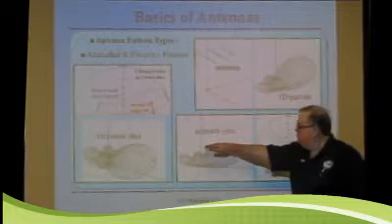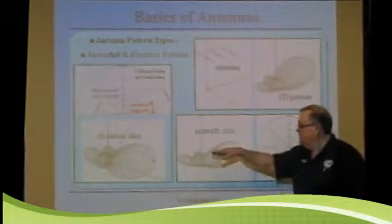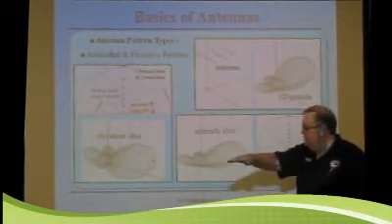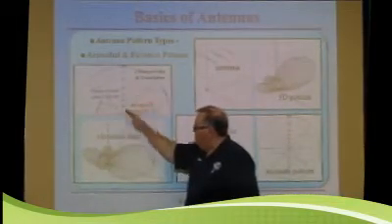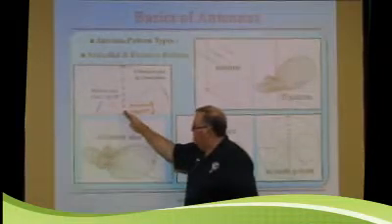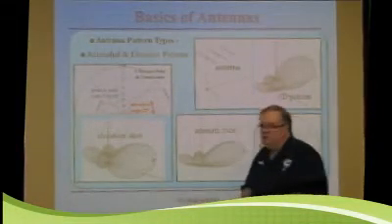When you get into gain, remember we're dealing with 3 dimensions here. You're dealing with your azimuth, which is the fancy way of saying north, south, east, west, the plane that we're looking at. Elevation is the height above the horizon of what your gain is, and really you're getting gain in both directions. So you can have gain that is up high, you can have gain that is in a certain direction. This shows an azimuth pattern of a typical beam.